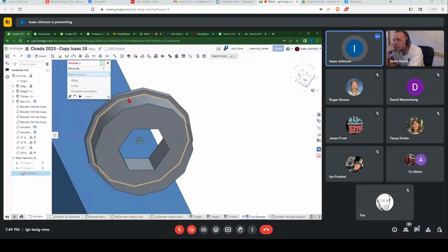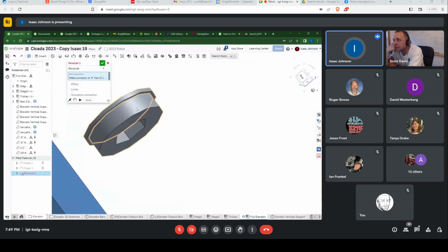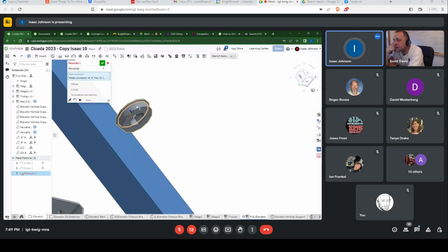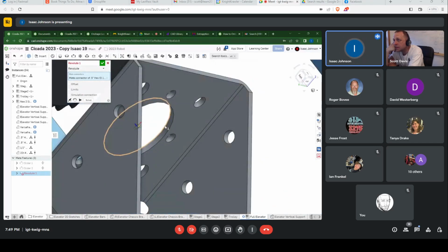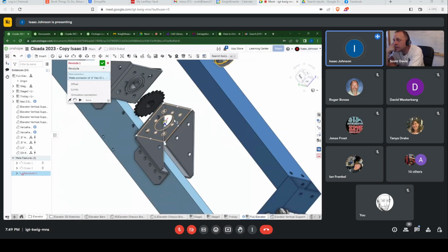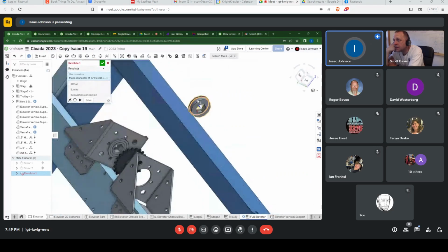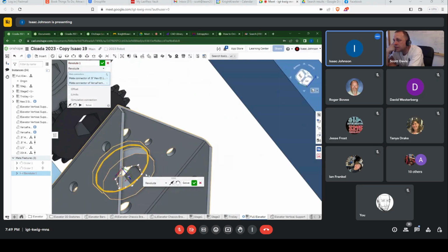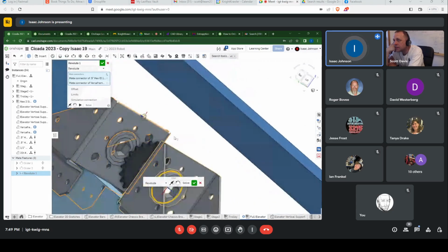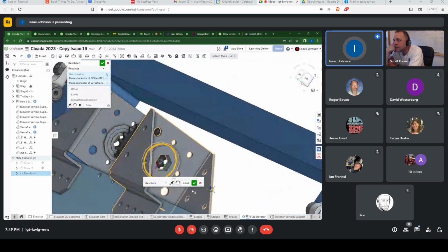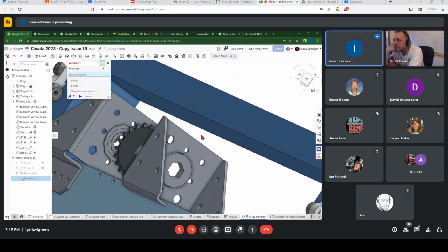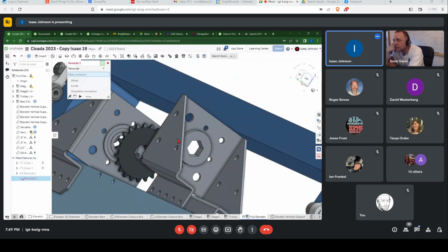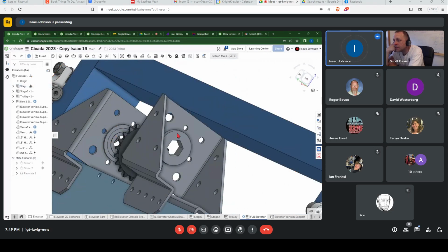So a revolute mate. If we take it here, you click the edge that you want it to go to. At first, with circular objects, it acts like a fasten mate, where you click the edge you want it to go and put it to the edge that you want it to be up against. But depending on how you put it on, since here it's two circles to each other, let me fix that real quick. It'll want to rotate because